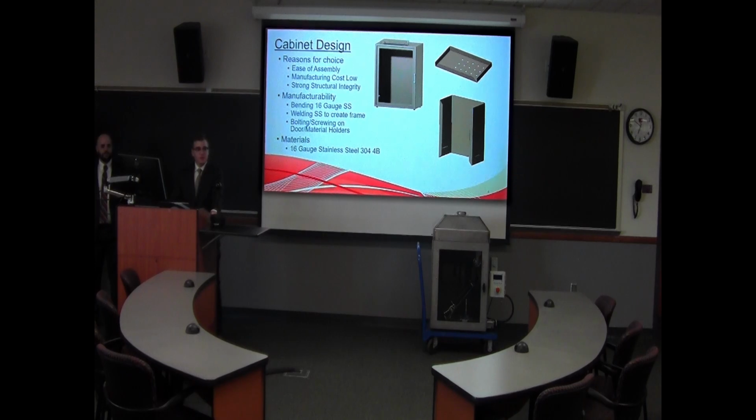While doing this, we also keep the manufacturing costs low by using the bent stainless steel sheet metal at 16 gauge thickness, which we use to bend to make these parts. Also, because of the welding, we significantly increase the structural integrity of the cabinet because now all the pieces, instead of 3 pieces, it's one single piece.